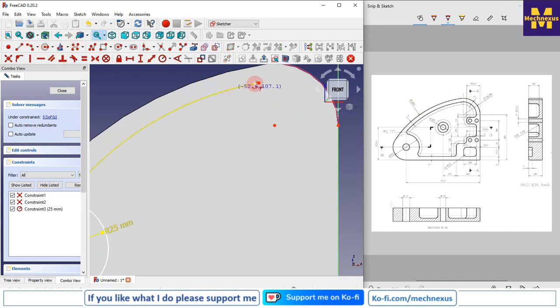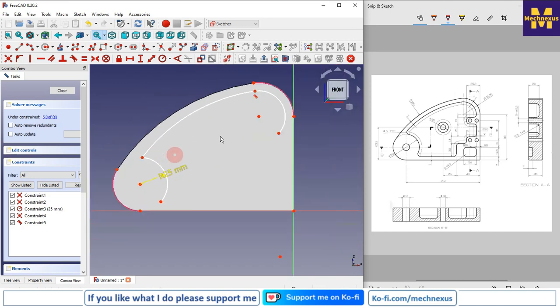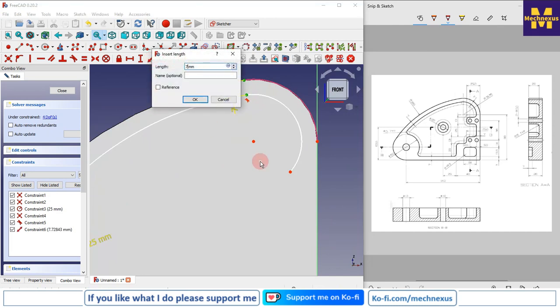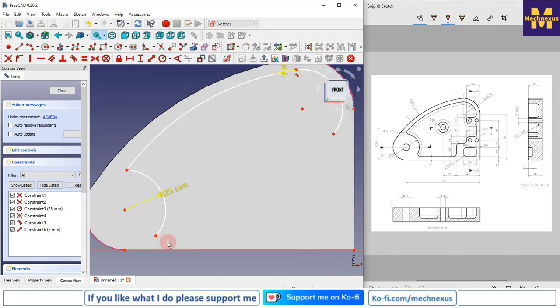So I will create a 3-point arc, and I will merge the center. I will make it tangent, and I will give the dimension of 7 mm, which is the wall thickness. And now I will draw a line here, and I will select the polyline feature, and I will draw my profile.